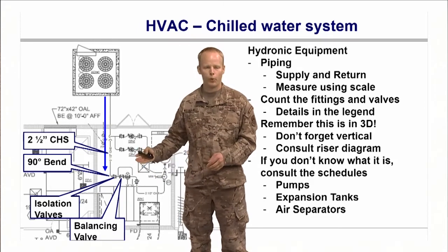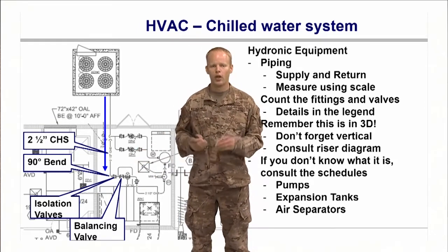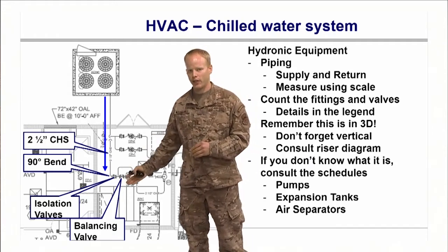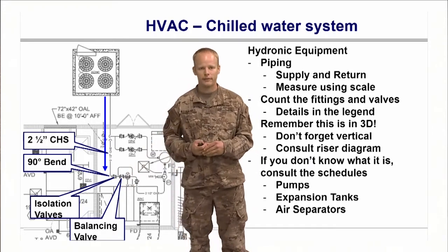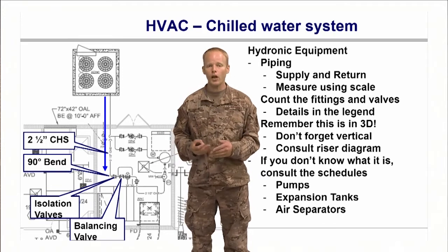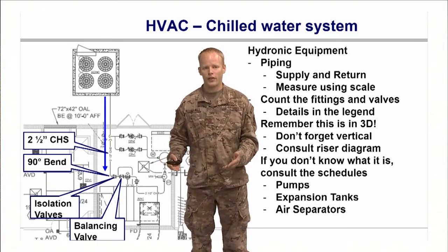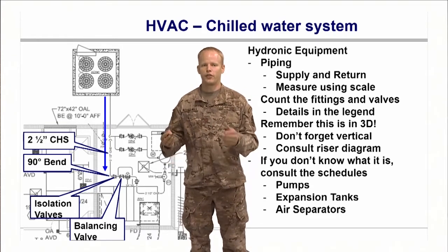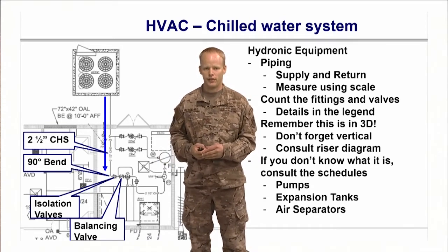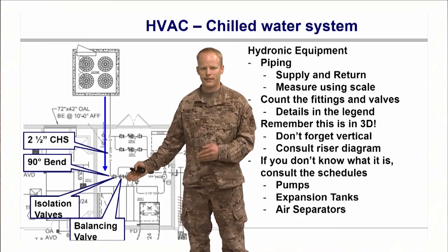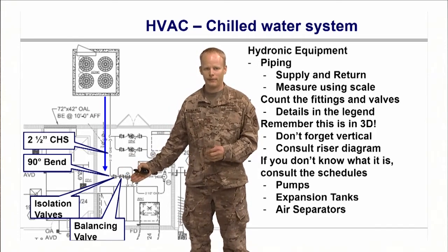But when you start talking about your multi-zone, multi-air handler systems, your more complicated systems, you are definitely going to have balancing valves around here. Also to be included with your balancing valves, don't forget the labor-only item, in that later you're going to have to do testing and balancing of this system. So for each balancing valve, you're going to have to add in testing and balancing to your estimate.